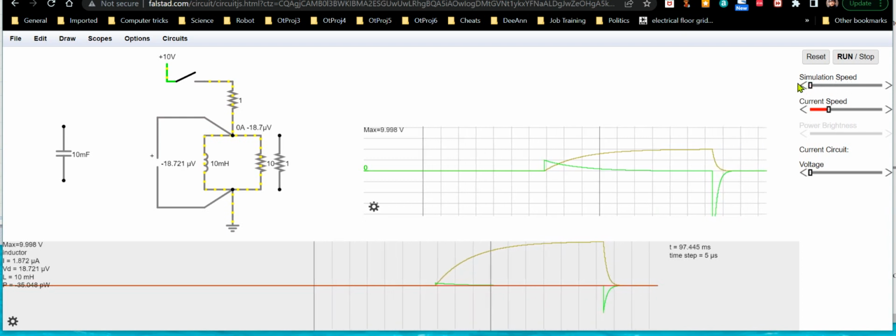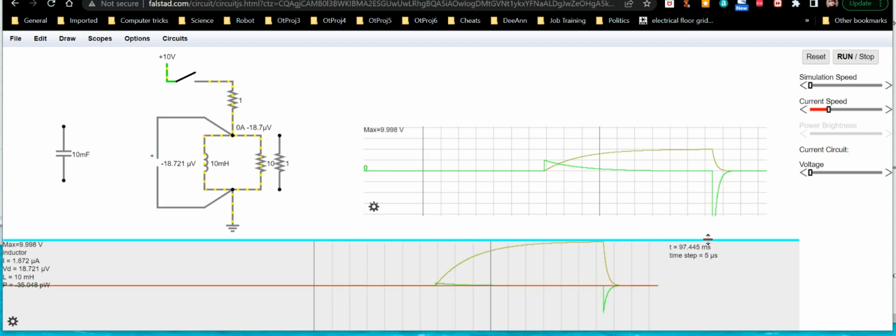That's why I have these at two different scales. That's why I set this scale up over here like I did, because you could see how the scale of this graph changed. Now all of a sudden this little voltage thing here looks small, but it's still at 10 volts, because that's what we charged it up at. But now you only see negative 64 volts because it goes off the graph. It's like 10 volts per division, so this is like 40 volts you can see there, but it's going to be about a 100 volt spike.